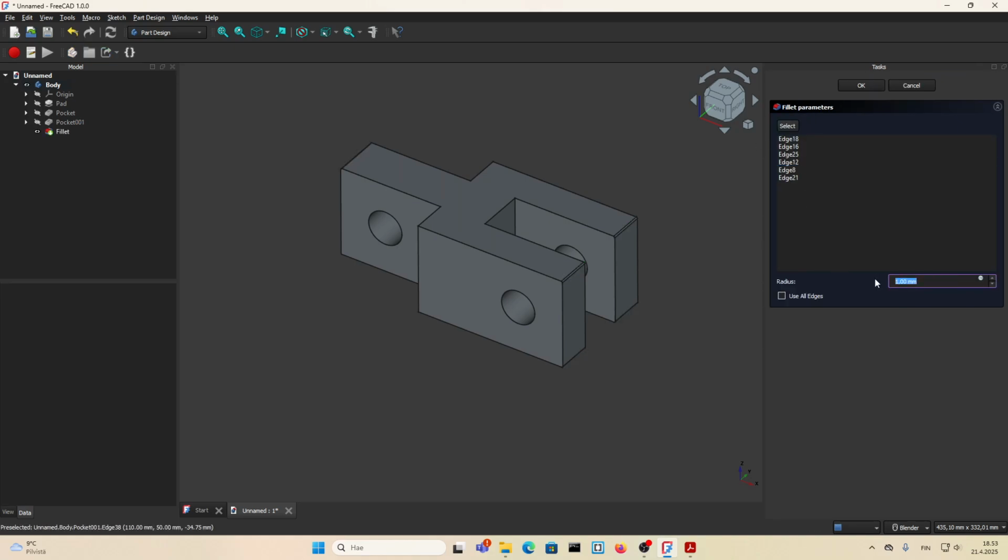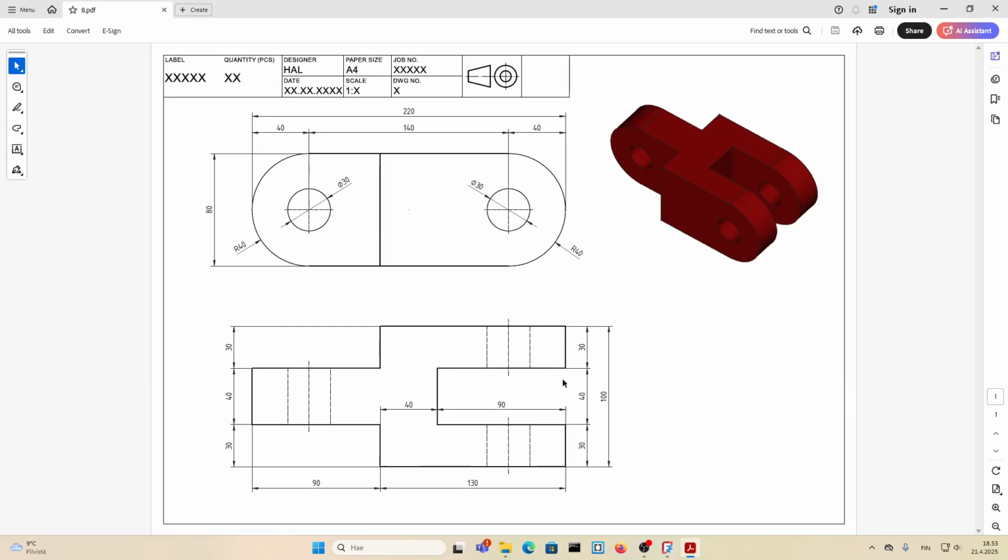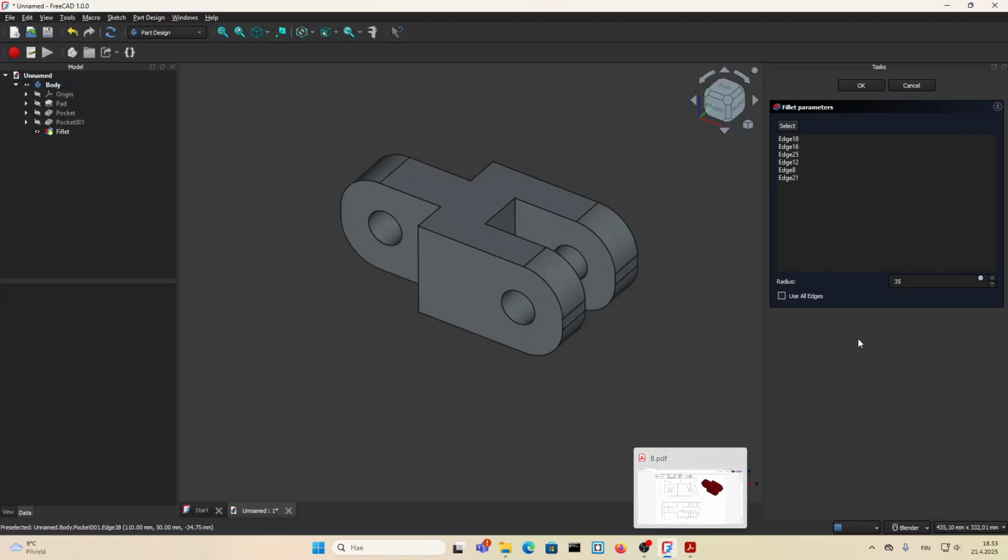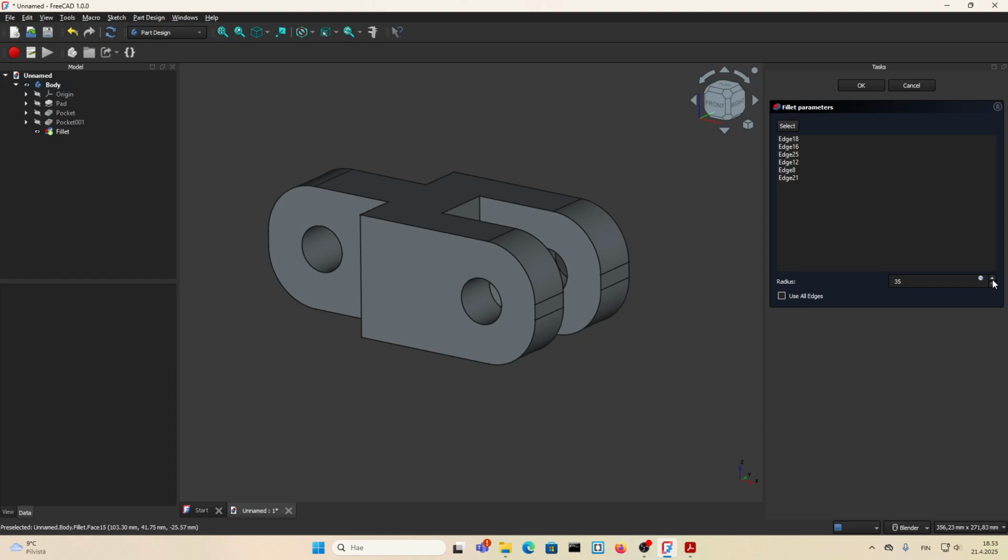Now take a look. I will repeat this lesson. In the drawing, it's 40, but if I put 35, everything is okay. The fillets come, everything's fine. 36, 37, 38, 39, everything is fine. If I put 40, in that situation it would become a full circle, an exact and precise circle. It will give me an error. Take a look. Boom, an error. It doesn't work. For some reason, this doesn't work.